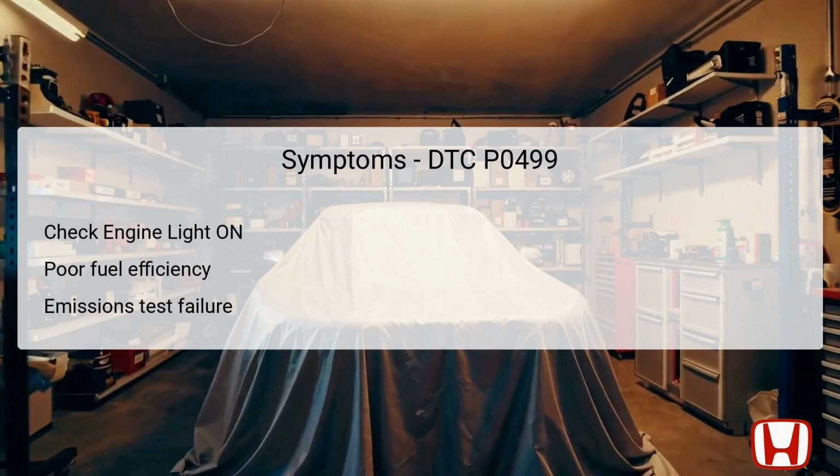Moreover, when the vehicle undergoes emissions testing, it may fail due to the inability to adequately manage fuel vapors, which can result in an emissions breach. In some instances, there could be a reduced performance under acceleration as a direct consequence of the valve malfunction. Recognizing these symptoms can prompt swift action to address the underlying issues indicated by the DTC P0499.